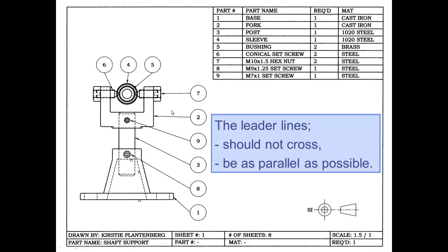Okay, so in this situation, the only thing that I want you to remember is please try to keep your balloons either horizontally aligned or vertically aligned, and do not cross them with each other. Okay, so the same laws that we learned before when we learned dimensioning still apply here.